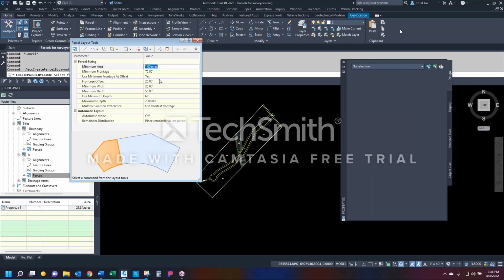Currently, the parcel minimum, I needed a 1 acre minimum. My frontage is supposed to be 75 feet from lot to lot. My frontage offset, and that's 75 feet based on that 25-foot front offset. Okay. Minimum width, 25. Minimum depth, 50. Do you want a maximum depth? In this case, no, because I don't know how shallow this is on this side over here.